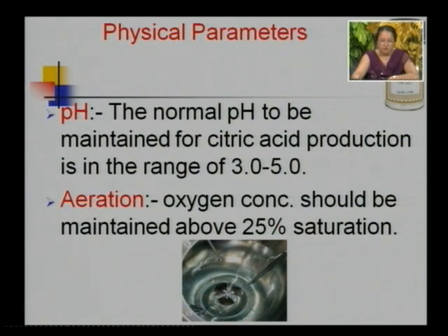The foaming. Forced aeration, if it is given in the beginning of the process, affects the microbial rate and citric acid productivity. If low aeration limits are there, it will restrict the respiratory activity of the Aspergillus niger. Strongly aerated cultures increase sporulation and thereby decrease the accumulation of citric acid.